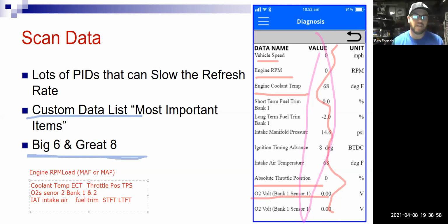the car is driving, okay? Again, engine speed, RPM, throttle position, and airflow, those things should all move up and down together, okay? Those should move together. And of course, if I crack open the throttle, we expect the mixture to go rich. And so the O2 sensors should signal that as well. They should say, okay, I'm going rich. And then if I let off on the throttle, the mixture should go lean, and I should see those things all move together, okay? So when I have a drivability issue, that the engine is running weird, running a certain way, that's what I'm looking at.